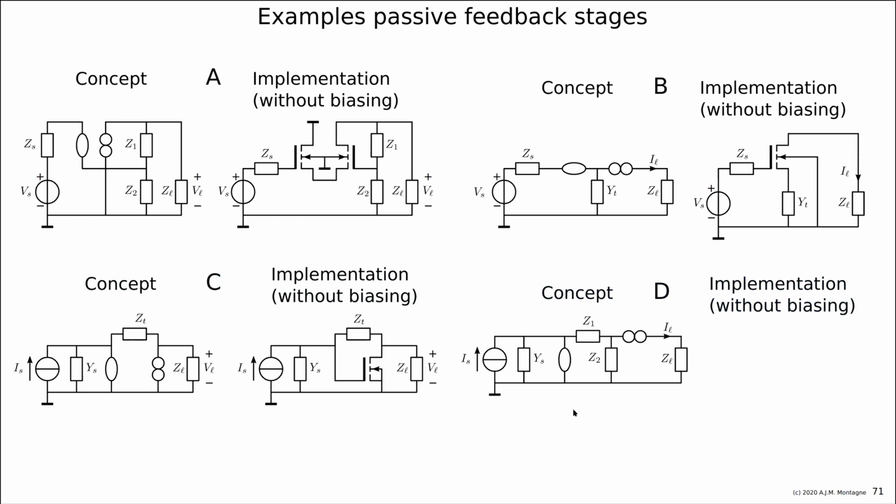And here you see again that we have no common terminal for the nullator and the norator. IL, which is flowing through the parallel connection of Z1 and Z2, and therefore only a part of IL is flowing to Z1, makes that the part of IL an accurate copy of IS because the voltage across YS is kept 0.